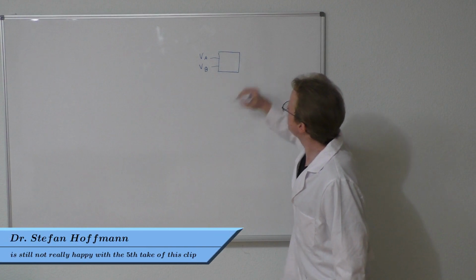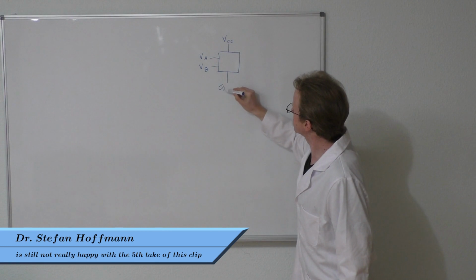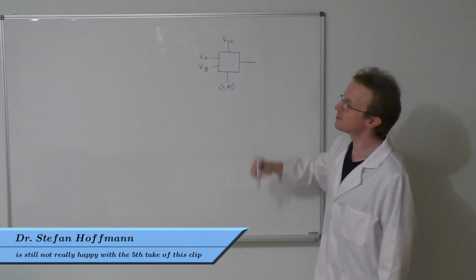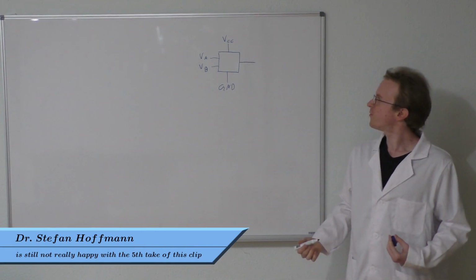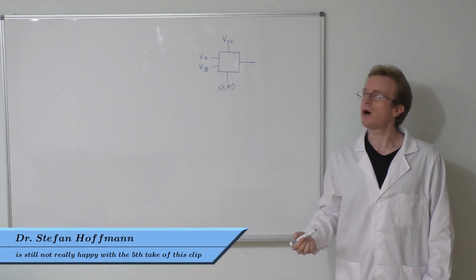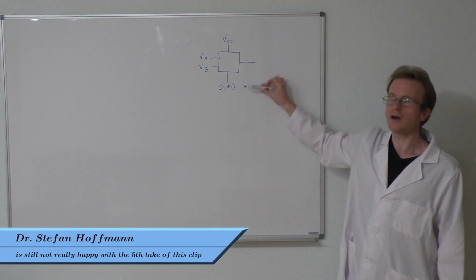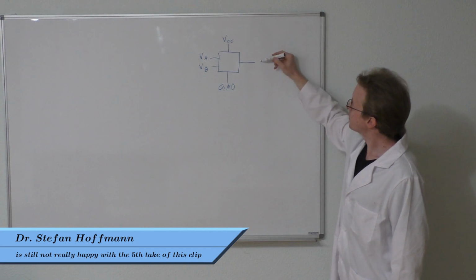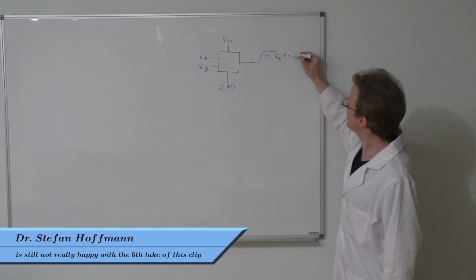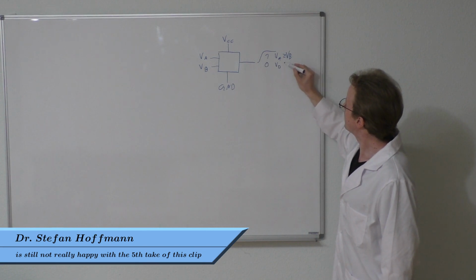That's supposed to be a B. And of course it also has a supply voltage and a ground reference. And this will output 1 bit of information. So the only output of an analog comparator is something that will read either a logical 1 corresponding to the supply voltage or a logical 0 corresponding to the ground. So what exactly will this output read? Well, it will read a 1 if VA is greater or equal to VB, or a 0 if that's not the case.